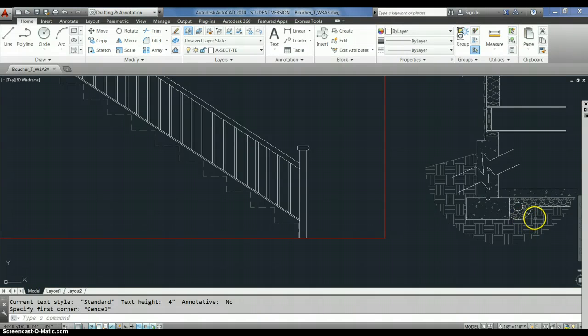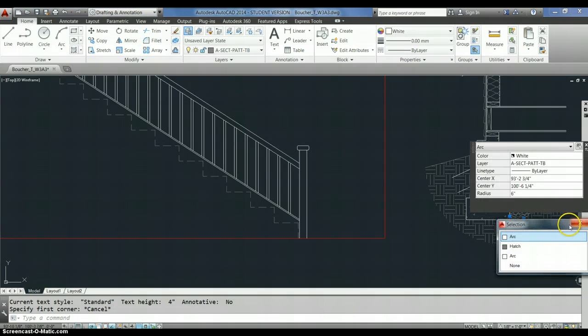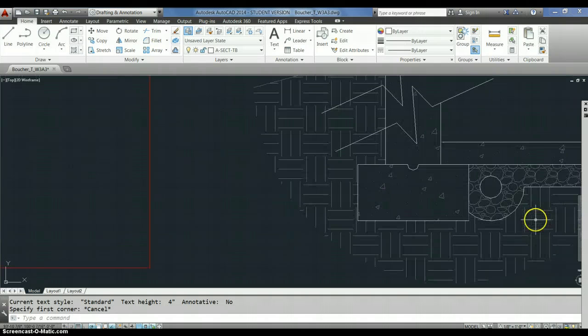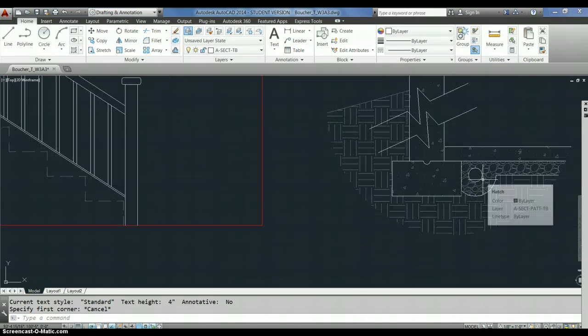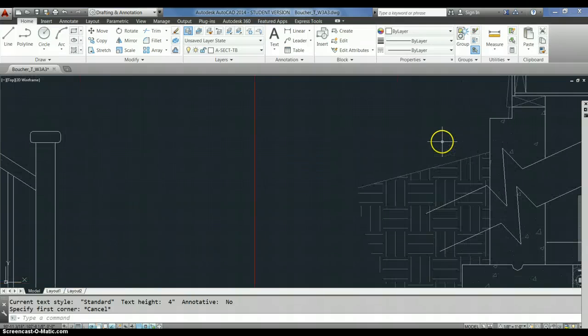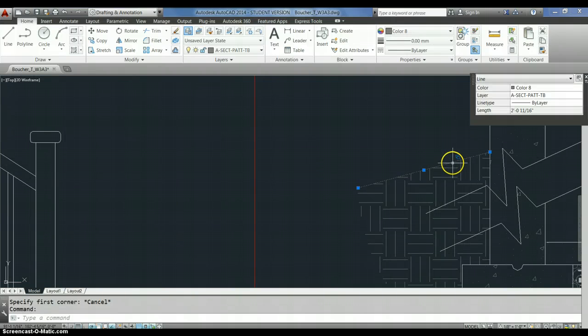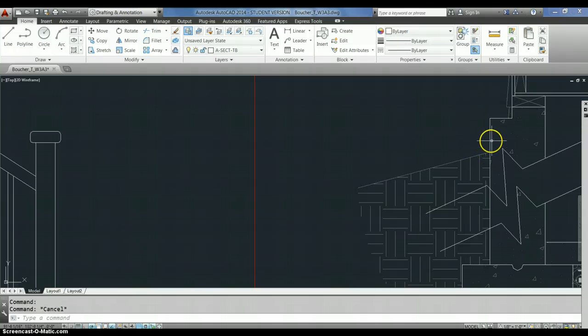Also, I typically will put this line in between these two hatches on the lighter layer because otherwise it reads too dark on the drawings. Once again, this is a finesse issue. I also show this on the same layer as the cut because it is a cut. Okay, so that one needs to be done. Here we go.